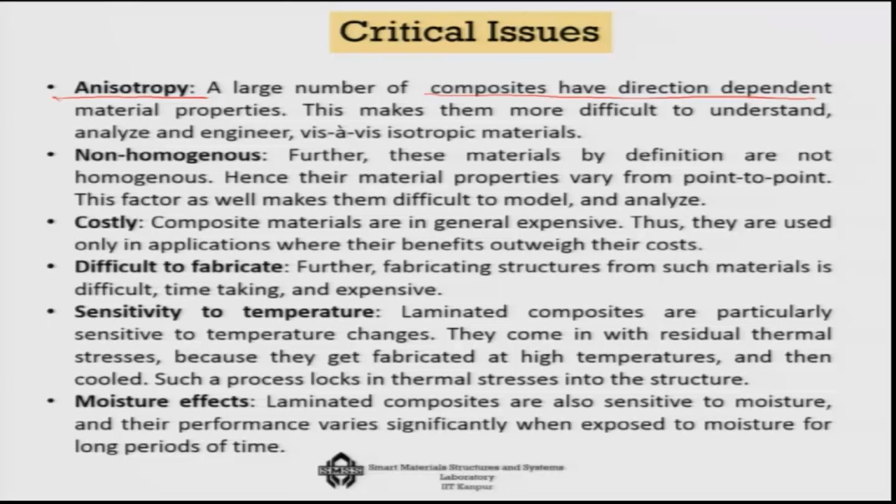Secondly, sometimes we cannot really control the process, like if you think of chopped SMA fibers or any such chopped fibers, then you cannot control how they are distributed. So, it will become non-homogeneous. So, that is a second critical issue. Well, cost of course, in some cases will be really important, particularly when we are developing systems which will be for mass use.